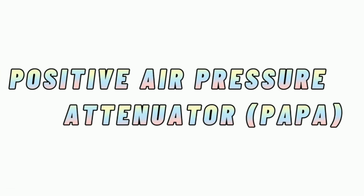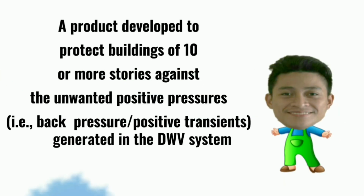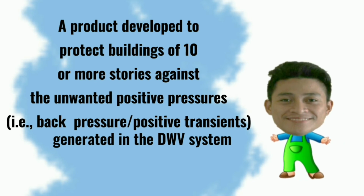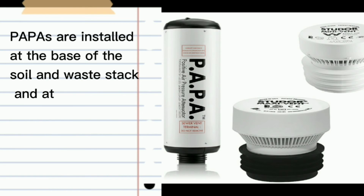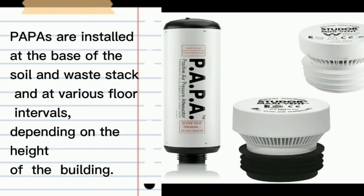Positive air pressure attenuator. Positive air pressure attenuator, or PAPA, is a product developed to protect buildings of 10 or more stories against unwanted positive pressure, for example back pressure generated in the DWV system. PAPA are installed at the base of the soil or waste stack, and at various floor intervals depending on the height of the building.